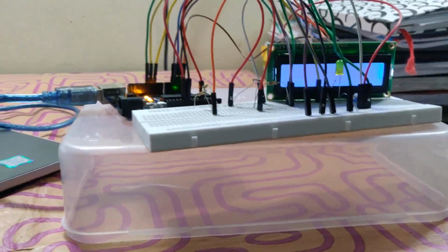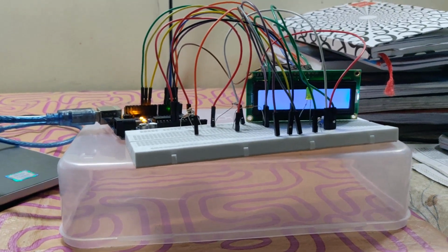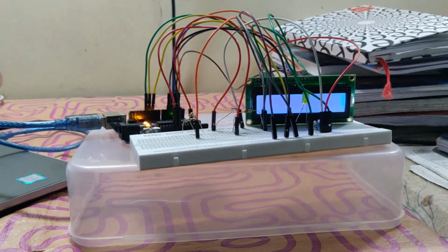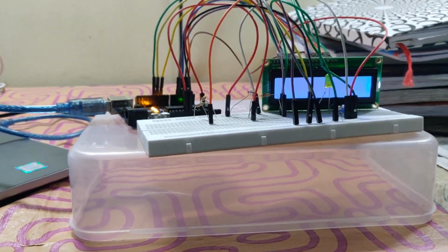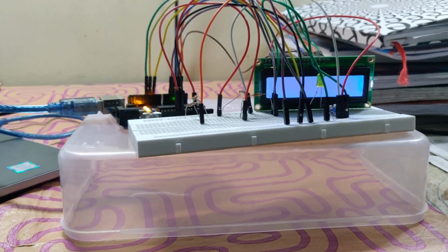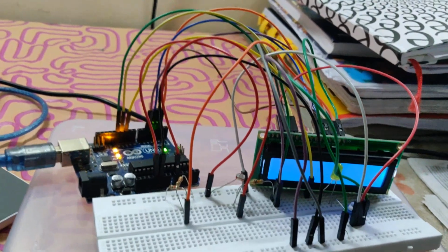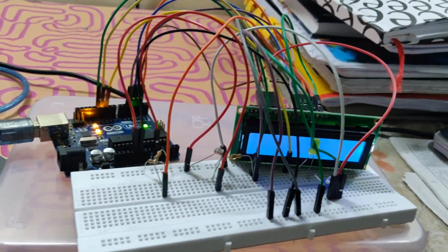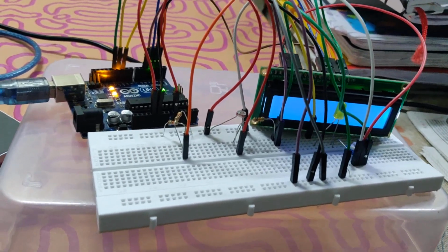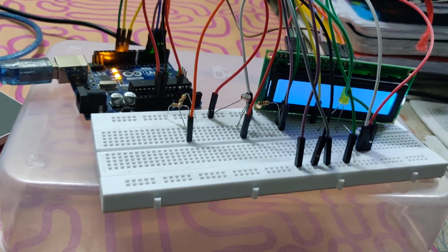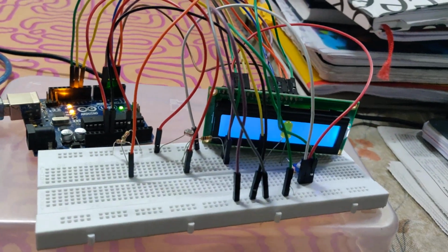Now actually before showing you the whole code, I will once again briefly list out all the implementation steps for the connections in the hardware. We will start by connecting the 5-volt output of the Arduino to the positive rail of the breadboard. Then we will connect the ground to the negative rail. After that, we place the LDR on the breadboard and attach the 10 kilo ohm resistor to one of the legs of the LDR.